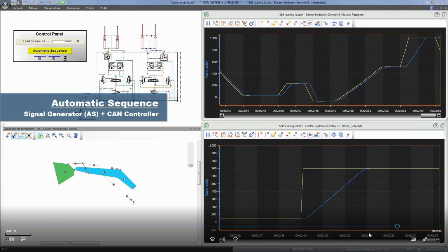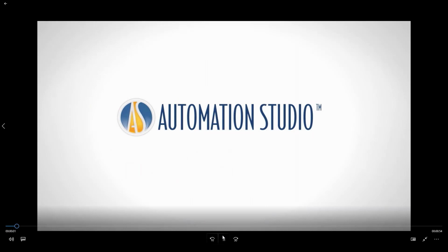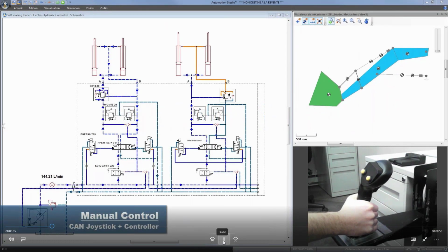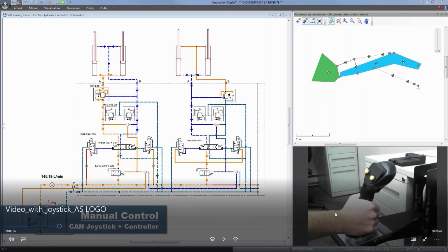Here we go. If I launch this, it's an example of the type of architecture that you can put together. On the bottom right you have a joystick which sends a value to a controller. This controller is linked, in that case, using CAN bus J1939 protocol. In the connectivity manager, the communication manager that Richard showed, you are able to easily link the input and output variables.